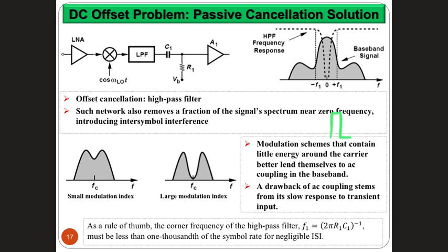Now, if this for some reason becomes wider, and that notch filter can cause that effect if it's very close to the rate of transmission, then this will have some value where you are trying to read the 0. You will end up with something that might even read as a 1, because of that spreading of the symbol. And each symbol will cause the same effect to the next one and so on. This is called inter-symbol interference.